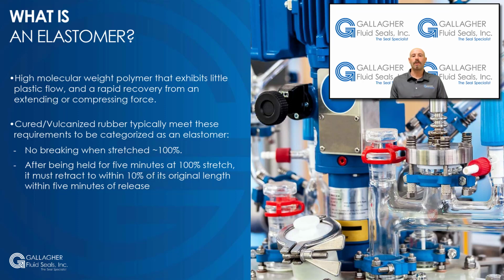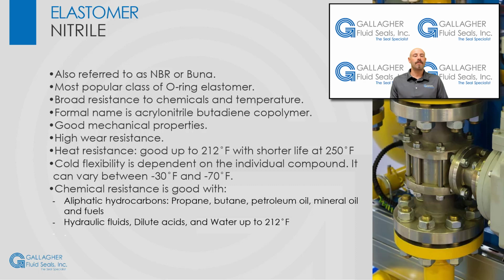Cured or vulcanized rubber generally meets the following requirements in order to be called an elastomer. It must not break when stretched approximately 100%. After being held for 5 minutes at 100% stretch, it must retract to within 10% of its original length within 5 minutes of release. The first elastomer that we are going to review is nitrile.